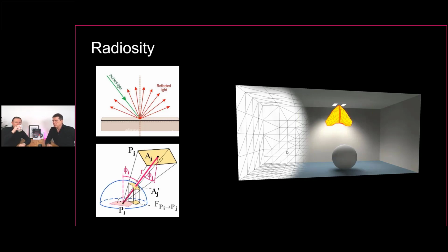In some extreme situations, for example, when you have a really large scene in your project and you use very small luminaires with very narrow light distribution, you should take this into account and start with a finer calculation grid, or otherwise you will lose too much light in terms of accuracy.